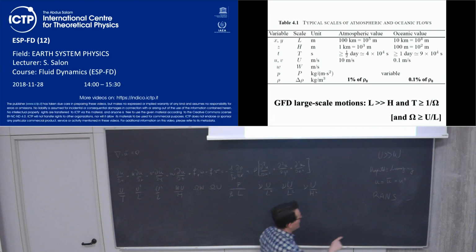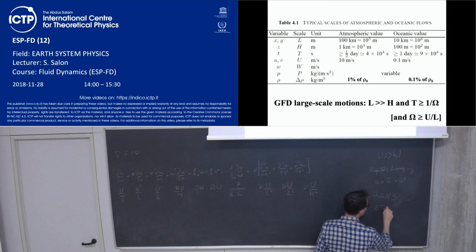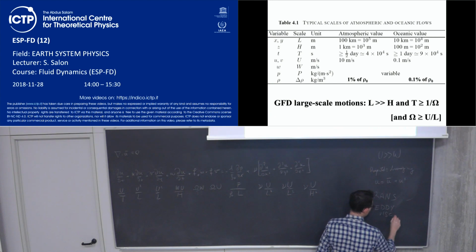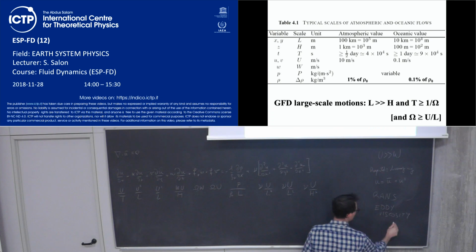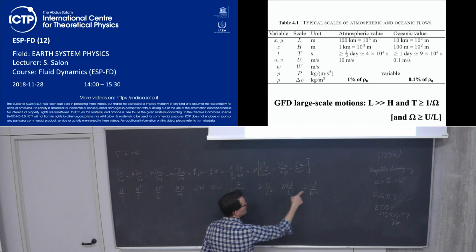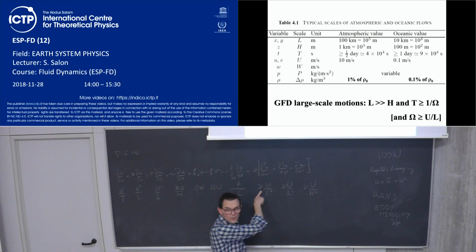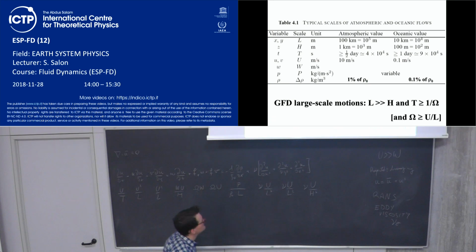Especially because at the end of this, you will find the definition of the eddy viscosity. So what is eddy viscosity, for which I use the letter E over the term mu? It means that this term here, if we follow our argument, is actually the molecular viscosity. So it is related to the fluid, which is water or air in our case.